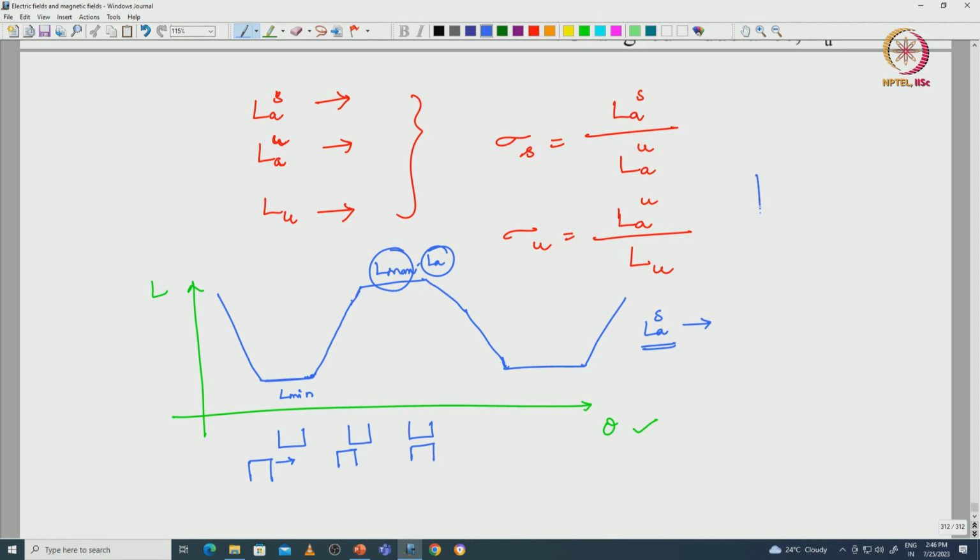And if we observe the torque waveform for the switched reluctance machine, at every instant we are exciting only one particular phase. So the torque developed by one particular phase is this one, and the torque shifts from one phase to the other. Because of that, we will see a huge ripple during the transition from one phase to the other. This is the transition.